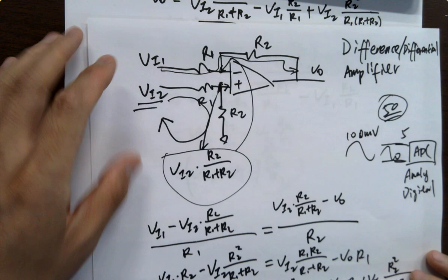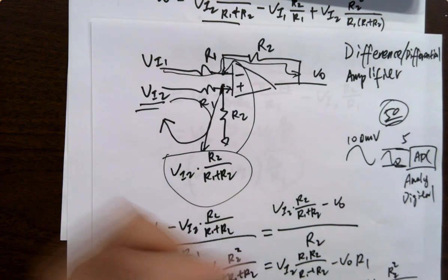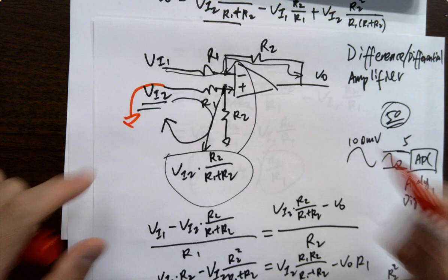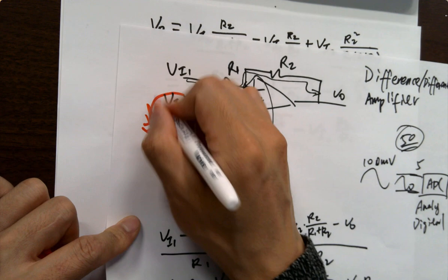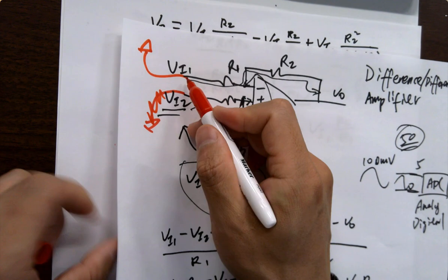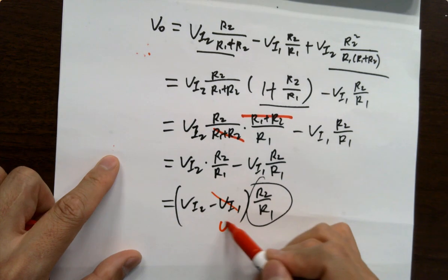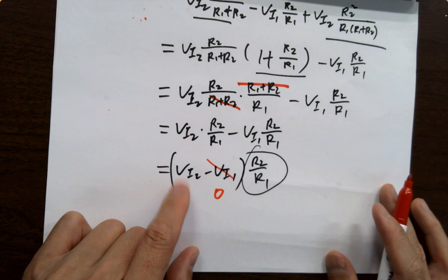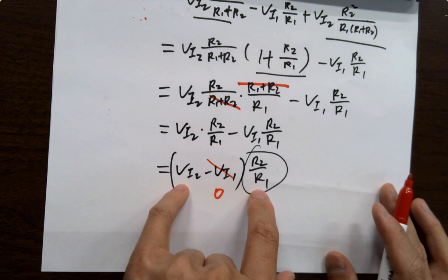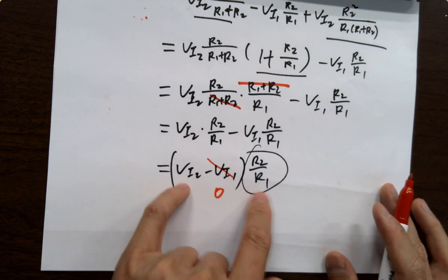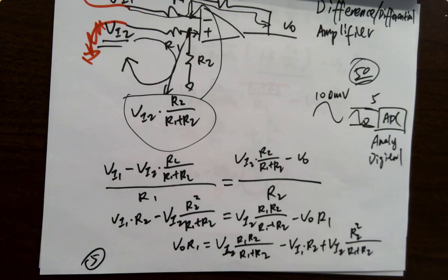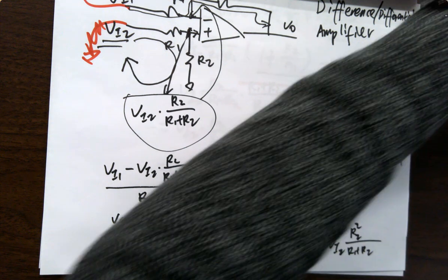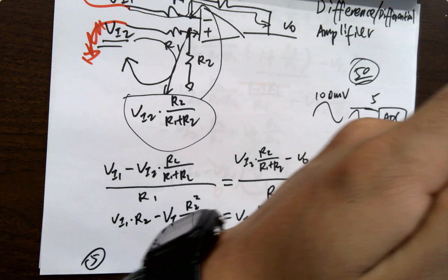So if I have two signals injecting into it, you can say, hey, I just want to ground one, which is okay. If you ground this guy, did I use V2 minus? If you ground the other guy, you're getting 0, so V2 minus 0. So it's amplifying VI2 directly, without anything getting inverted. That's a really practical amplifier circuit. So this one is being used for this problem.